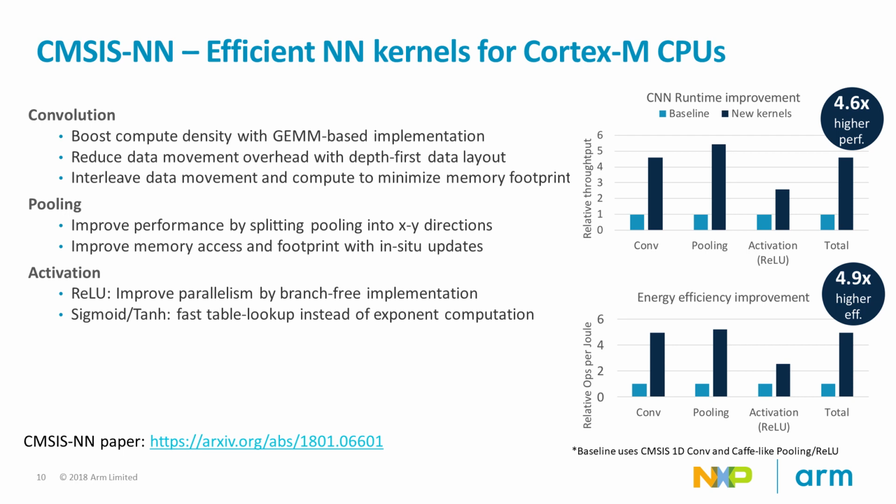The standard implementation of the keyword spotting neural network would actually require a Cortex-M processor with around 60 MHz, but this processor would be utilized 100% to run the network. Reducing that to a fifth means that you actually gain 80% CPU runtime for other tasks. If you now extrapolate that up to the i.MX RT that actually runs at 10 times the processor speed, you see that the neural network execution time actually gets a 1-digit percentage of your total CPU time, and it's just another side task that can just be easily run even next to a complex application.